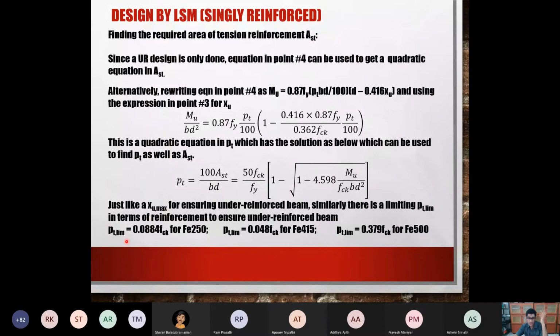Over reinforced. Okay, it becomes over reinforced and you don't want it to be over reinforced. Now you have two options. One is reduce the steel. Okay, so you require a certain amount of steel to take the tension. But if you reduce the steel, what will happen? Just because it's over reinforced and you don't want it to be over reinforced, if you decide that let me reduce the steel which I am giving, is it okay or is it a problem?